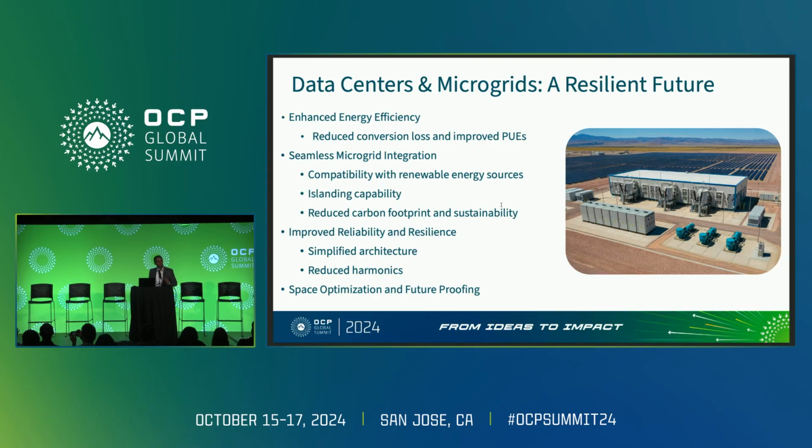We can also enable seamless transition, whether you're utility connected or connected to your local on-site generation within the microgrid, without creating sags and swells or disturbances to the downstream loads, ultimately improving the reliability and the resiliency, right? Outside the data center space, microgrids are a well-matured space, whether it's petrochemical, oil and gas, different kinds of industrials, and even utilities that are adopting them, primarily to protect themselves from all sorts of grid disturbances, but also to enable and integrate renewable energy sources